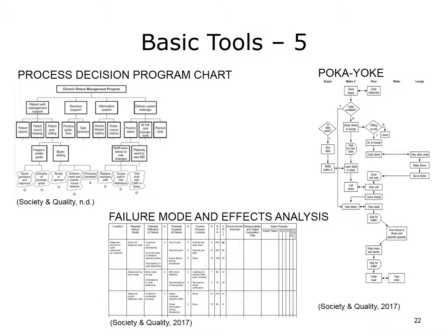Poka-yoke, the Japanese term for mistake-proofing, means paying careful attention to every activity in a process to place checks and problem prevention measures at each step. Mistake-proofing can be thought of as an extension of FMEA. Whereas FMEA helps in the prediction and prevention of problems, mistake-proofing emphasizes the detection and correction of mistakes before they become defects delivered to customers. Poka-yoke puts special attention on human error.